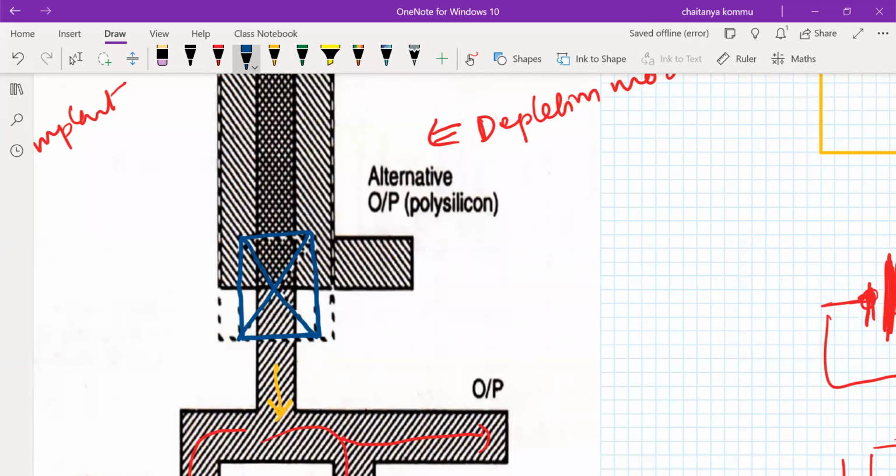So how have they done this? Another question. What we have to do is, at the bottom of the channel, towards the diffusion side, we have to maintain 2 lambda. But towards the polysilicon side, this side, we have to maintain 1 lambda. This is the polysilicon, and these are all the diffusions. That's the reason why this should be 4 lambda.